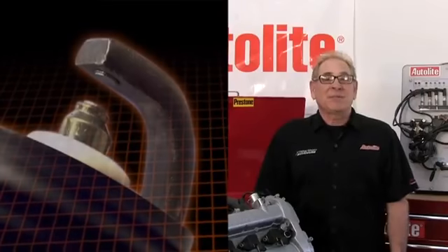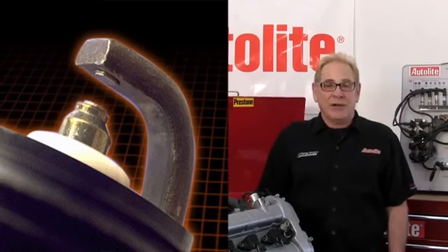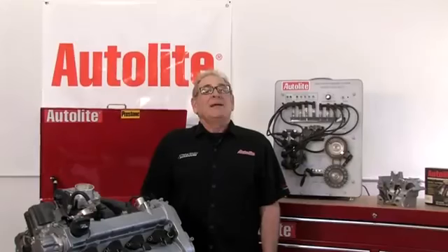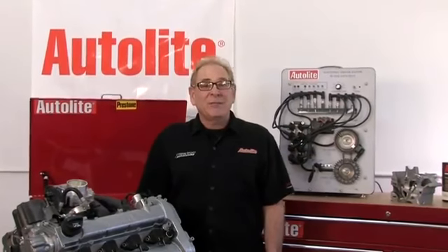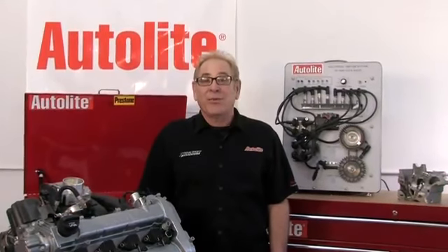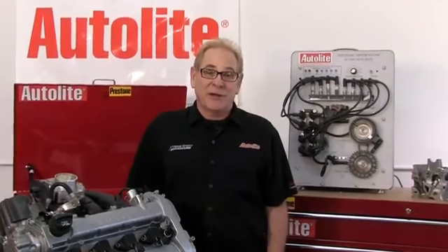If you think about the spark plug in an electrical circuit, the gap between the center wire and side wire is an open circuit. In order for the coil energy to jump that gap, the atoms in the combustion chamber will ionize to the point of plasma. They will conduct electricity and the plug will fire.